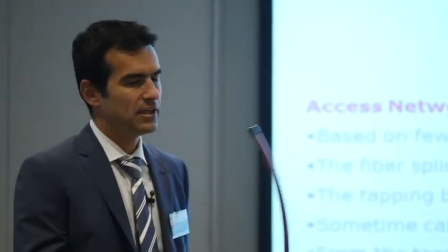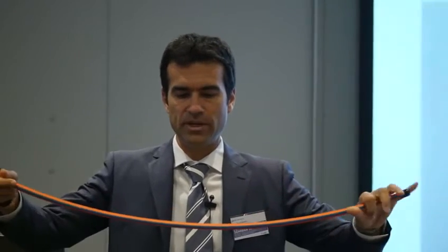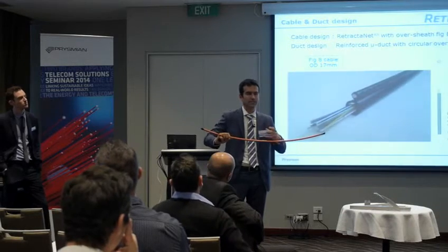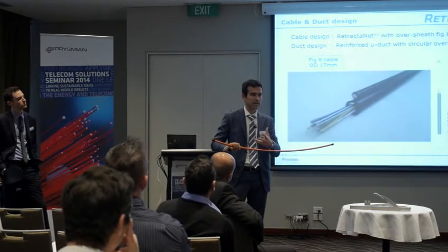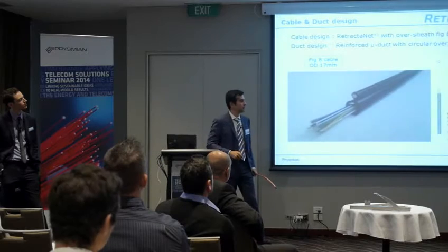As I said, on aerial, we were a bit afraid at the beginning, because when aerial cables are laid and you have ice, you have a deformation, or important deformation, which means that the cable can be elongated, and the fibers inside have to follow. So the construction with the stranded tube generally avoids that when the sheath is elongated, the fiber will suffer any stress. Then with a better fiber, and anyway the right construction of the cable, we've been able to solve also this one. And you see that actually the solution was just to use a figure-of-8 cable.